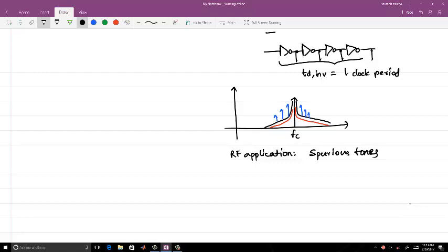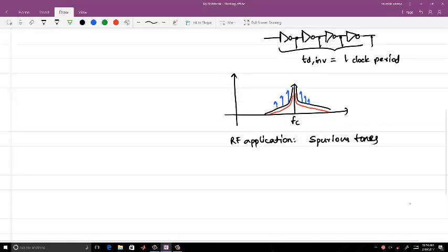So you have a signal in a narrowband, and all other channels are occupied by other signals in the spectrum, which might not be the required signal. If you have huge spurious tones in the clock source which you are using to down convert, so what do you have? You have an incoming RF signal, the desired RF signal, which is narrowband.